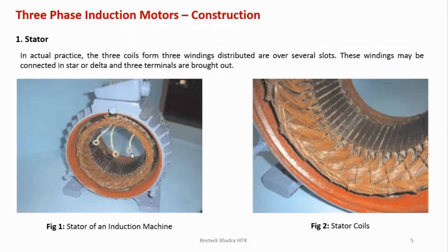What do these three windings signify? It is a three-phase motor. To one, the first phase, A phase, will be connected, to another B phase, to the other C phase. So this is the three-phase stator winding. And this is winding. This is not a rotating part. It is just a structure in which only windings are placed in slots. So this is placed like this.